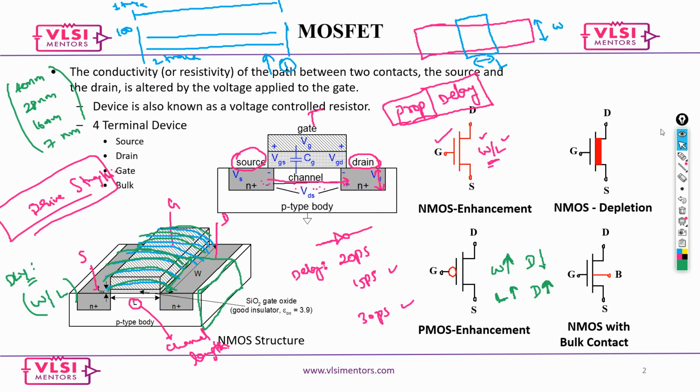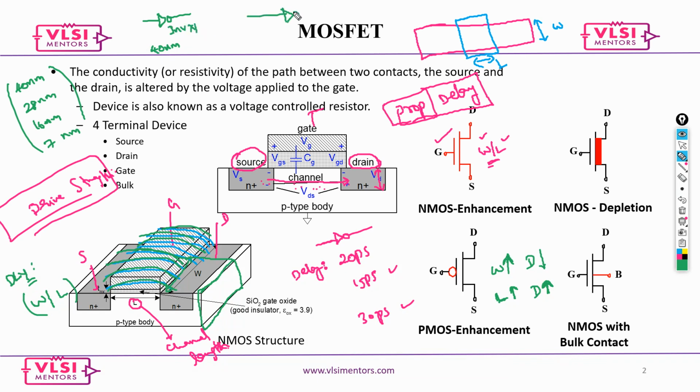Okay. Now, assuming the same cell, say you are going for an inverter which is manufactured in 40 nanometer, and you have an inverter that is manufactured in 28 nanometer. Assume this is an inverter X1, and here also the same inverter X1 in 28 nm. Now, what would the delay be? Delay will decrease. The 40 nanometer has more delay, 28 nanometer less.